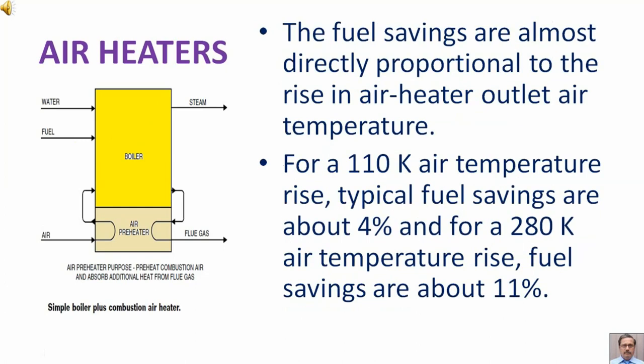The fuel savings are almost directly proportional to the rise in air heater outlet air temperature. For a 110 K air temperature rise, typical fuel savings are about 4%, and for a 280 K air temperature rise, fuel savings are about 11%.